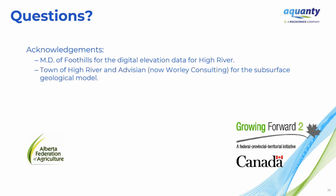But in general, HydroGeoSphere is flexible to model inputs, right? It's up to the user to define the temporal and spatial resolution of their input data. But you do need to keep in mind that the temporal resolution of your forcing data will also have significant impacts on the model runtime. With daily or sub-daily boundary condition forcing data, for example, you would by definition restrict your time step sizes to whatever the temporal resolution of that data is. But in general, HGS can handle whatever you throw at it.